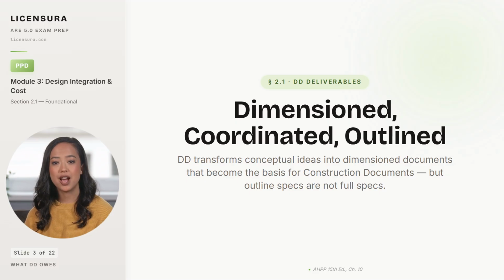Here's the trap most architects walk straight into during design development: thinking that outline specifications count as specifications. They do not, and the difference shows up the day you get sued for an installation method nobody documented. By the end of DD, you owe the owner 6 things: dimensioned floor plans, coordinated building sections, exterior elevations with material indications, preliminary wall sections, reflected ceiling plans, and outline specifications.